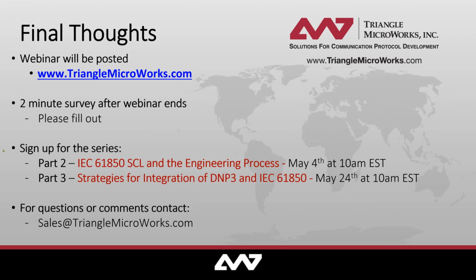Okay. My actual question is, how would you carry out an integration of the IEC 61850 protocol between two substations, one more modern with the protocol already integrated between relays and PLCs, and one a bit older using older methods of communication and control? So that's actually a large topic of webinar 3. Christoph, if you have more to add, then please do. But there are certainly methods of upgrading your existing substation to 61850 or integrating with a substation which uses older protocols, for example, DNP3 or 101, 104, something like that. You could use data concentrators, or you could use some of the engineering processes that we'll be talking about during webinar number 3.